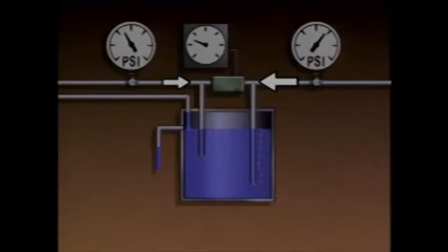As long as the liquid is maintained at a constant level by an overflow pipe, the difference in pressure across the DP cell caused by the difference in tube length remains constant. This means that any change in differential pressure across the DP cell can be attributed to a change in the density of the liquid. An indicator that's connected to the DP cell displays the density indication. Often, the density indication is expressed as a % concentration of a particular substance in the liquid.